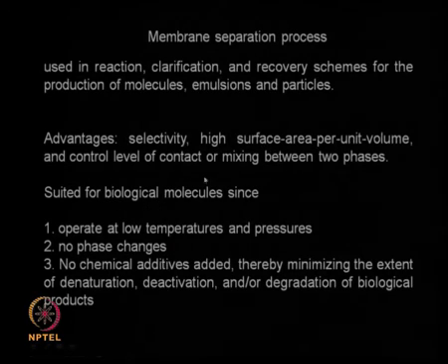They are suited for biological molecules because the separation can be done in ambient conditions, so the biological molecules do not lose their activity. The membranes can be operated at low temperatures and at pressures ranging from vacuum right up to 40-50 bar, especially the reverse osmosis membranes, which are operated at very large pressure, where we can desalinate salt water, that means marine water, into potable water.